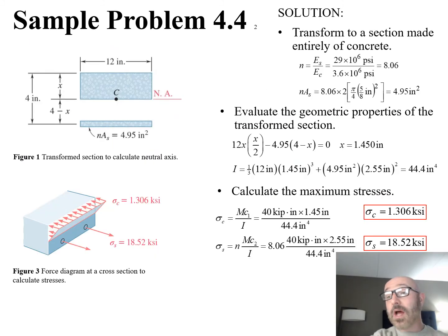So now that we've had that opportunity to read through the problem statement, create our setup page, write down all of our given information, and create a procedure for analysis in order to answer what they've asked us to solve for, what we want to do now is create a diagram right here, transforming the section into a section made entirely of concrete.